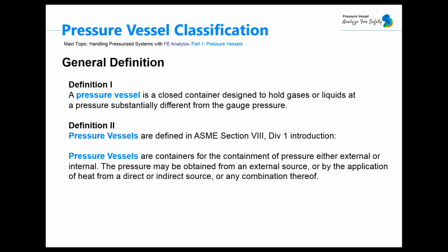The term vessel means a housing designed and built to contain fluids under pressure, including its direct attachments up to the coupling point connecting it to other equipment. Generally a vessel may be composed of more than one chamber, and I'm citing this ASME again because it's very important to know that today we will not talk about the pressure containers which are integral parts or components of mechanical devices like pumps, compressors, turbines, hydraulic or pneumatic cylinders.